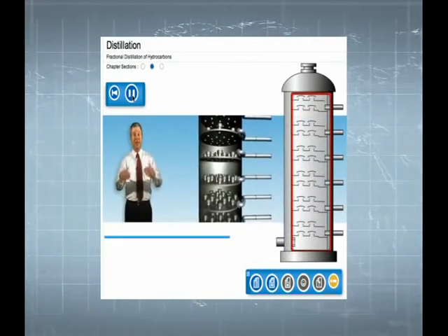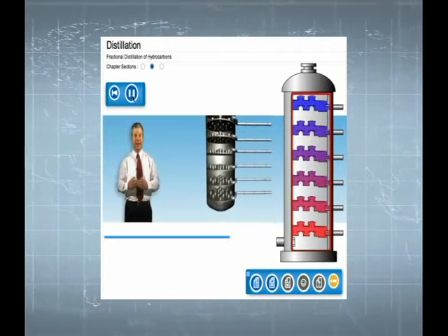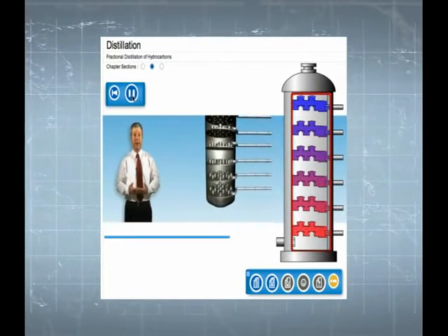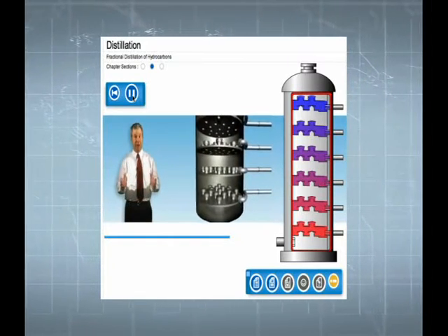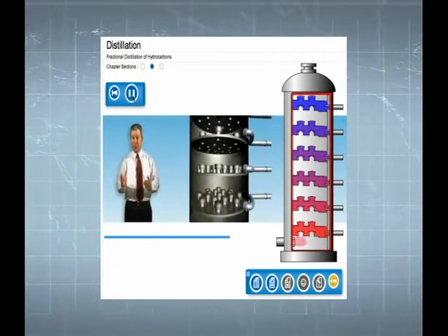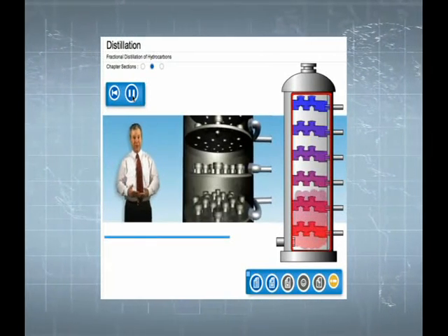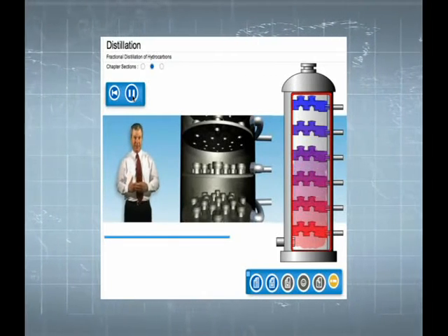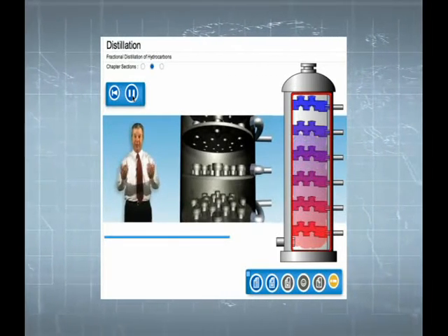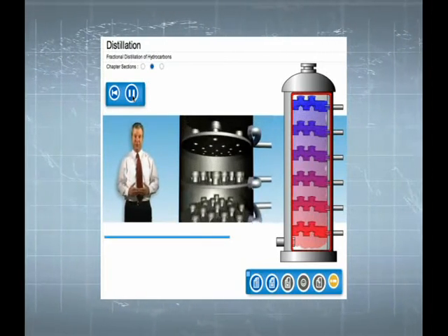The trays are set at heights that correspond to specific temperatures in the column. Obviously, the lower in the column a plate is set, the higher the temperature the plate corresponds to, since the vapor cools as it rises in the column. Therefore, the lower trays in the column will condense fractions that condense at high temperatures, and the trays set higher in the column will condense the fractions that condense at lower temperatures.